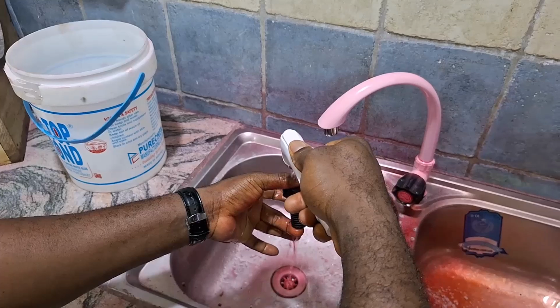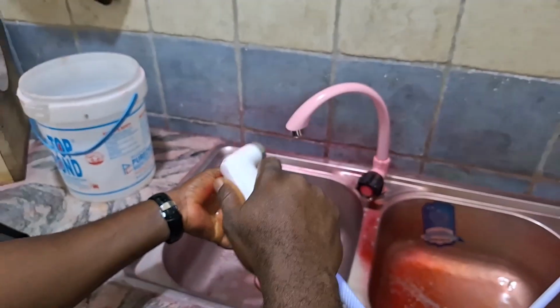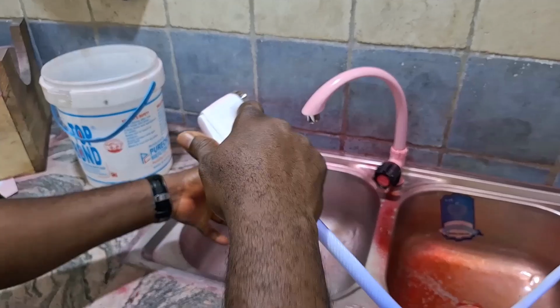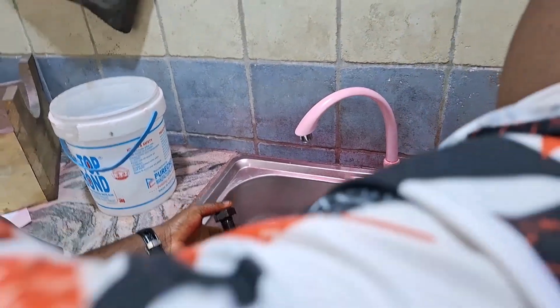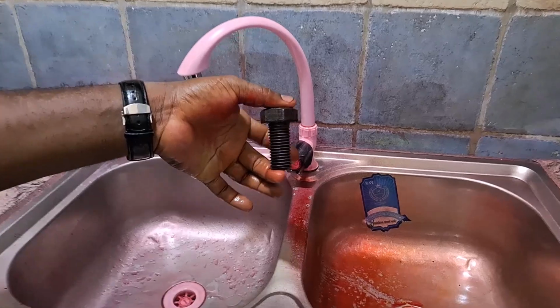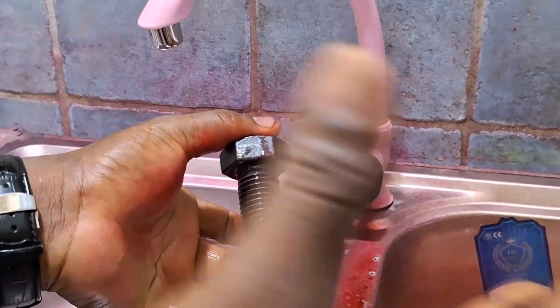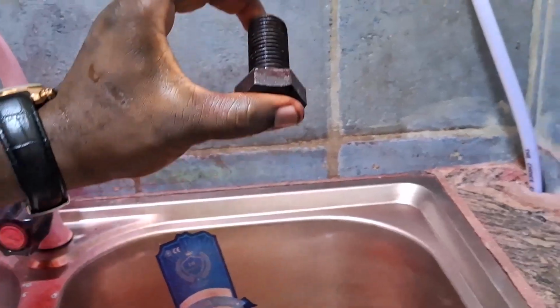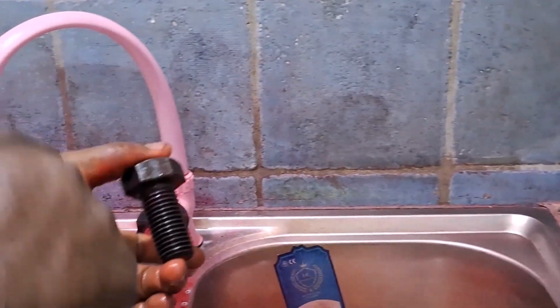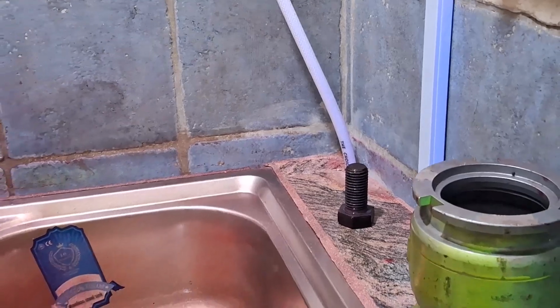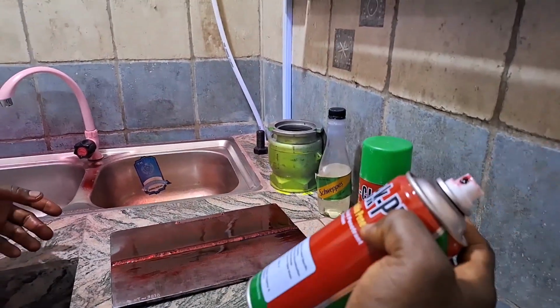This is the water washable. So it's very important that you consider your water pressure. Normally, it should be within 15 psi, so that you don't excessively wash out the penetrant and remove those ones that are supposed to be in the crack. In the case of our solvent removable, you just